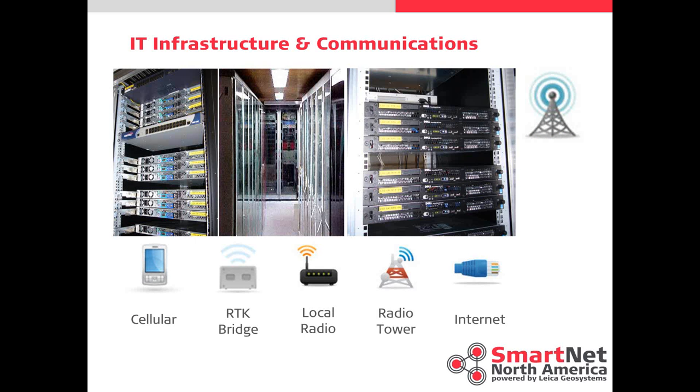IT infrastructure and communications is important both on the server side, where the receiver to the server, as well as from the server to the users out in the field. This, of course, is the largest point of failure that we run into on a day-to-day basis. The software is very stout. The receivers out there in the field are very stout. The monumentation out in the field is very stout. The usual failing point is here in the comms, either from the receiver to us because of cable modem or DSL going down, local IT changes, firewall changes, interrupting the data flow from the receiver to us, or vice versa.